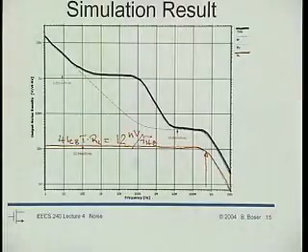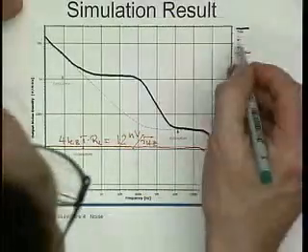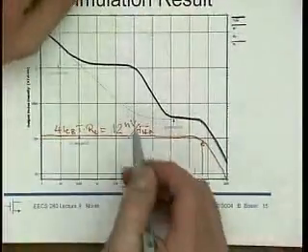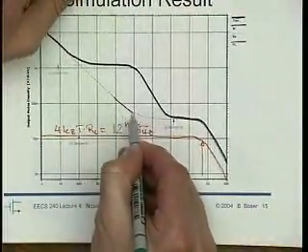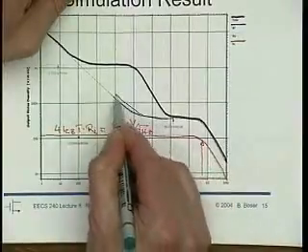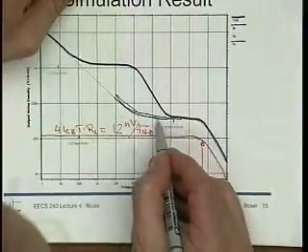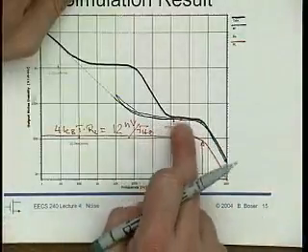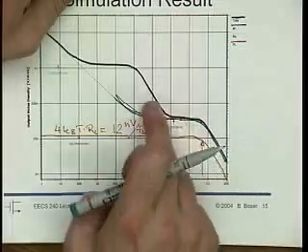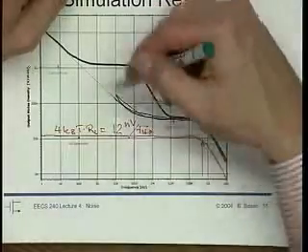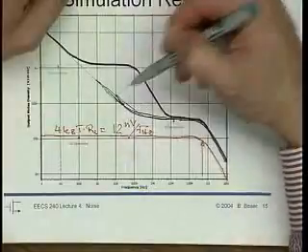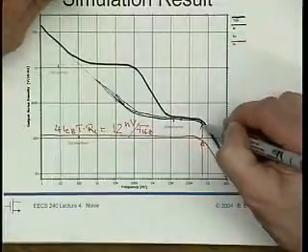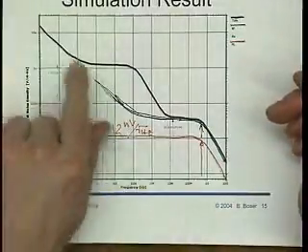Okay, so now let's look at the transistor M1, and the noise from its current noise generator, and that's shown here. It rolls off here. So apparently the transistor dominates noise at higher frequencies here, and then here it's something else that contributes. What is this thing here? This is again 600 megahertz, right? We would expect that. But what is this thing here?